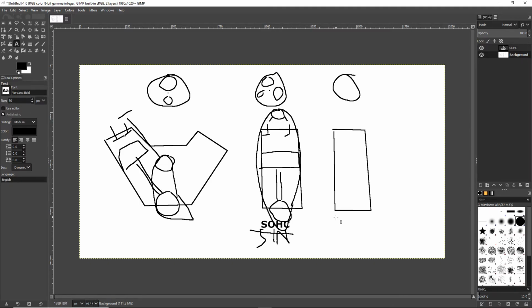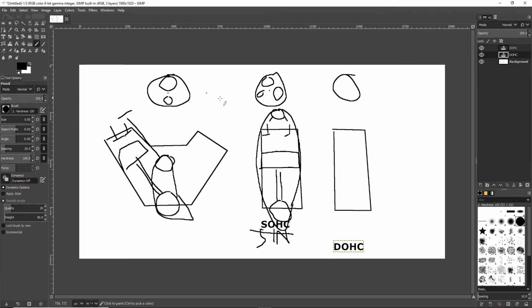And we put it over the head. And then the other one that you may have seen on the side of the Civic, double overhead cam. So what we're going to do now is put 2 camshafts, double, over the head, and now this one can hit just the intake valves, and this one over here can hit just the exhaust valves. My drawing is so terrible. We can get 4 valves per cylinder.